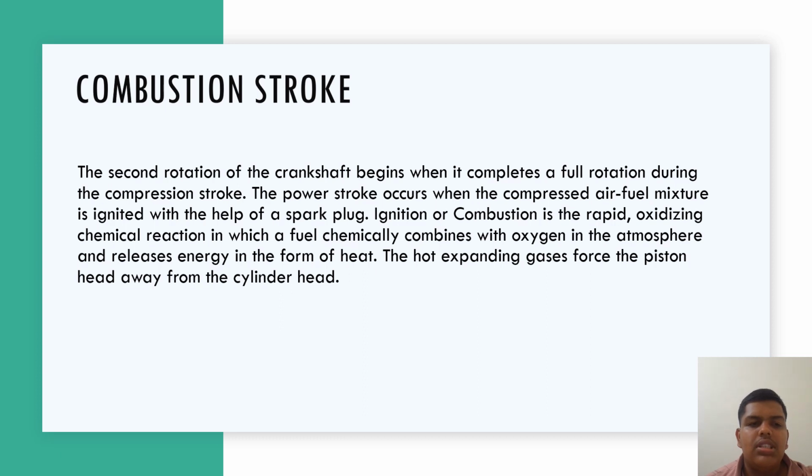Combustion stroke. The second rotation of the crankshaft begins when it completes a full rotation during the compression stroke. The power stroke occurs when the compressed air-fuel mixture is ignited with the help of the spark plug. Ignition or combustion is the rapid oxidizing chemical reaction in which a fuel chemically combines with oxygen in the atmosphere and releases energy in the form of heat. The hot expanding gases force the piston head away from the cylinder head.